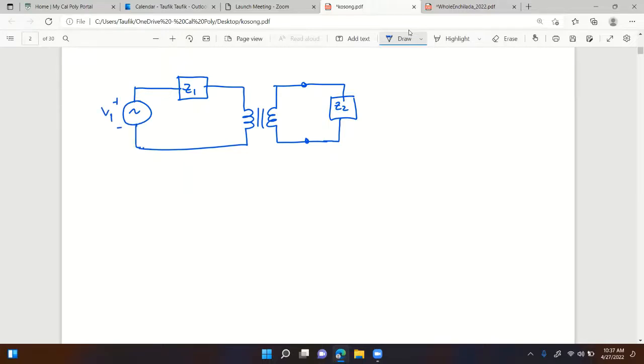If you have a circuit like this, then one of the ways to solve for, let's say, currents in the circuit would be using 2 loops, right? So there are 2 loop equations, from loop number 1 and loop number 2, which is fine, but keep in mind that you have a turns ratio here. So there is some complication, because not only do you have to do 2 loops, but you also have to pay attention to the turns ratio, and also to the signs of the turns ratio.